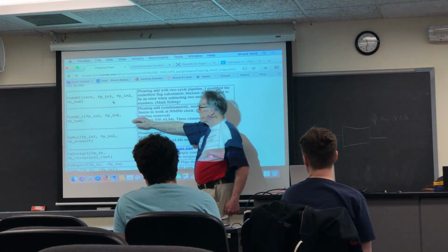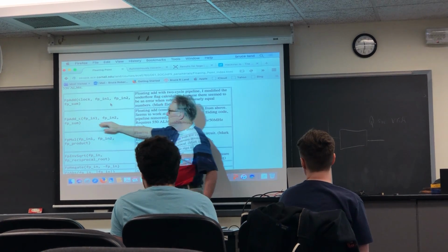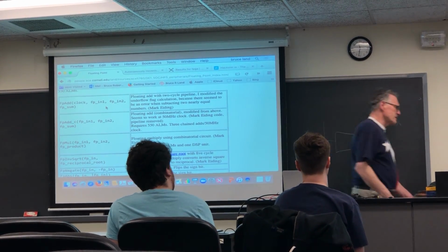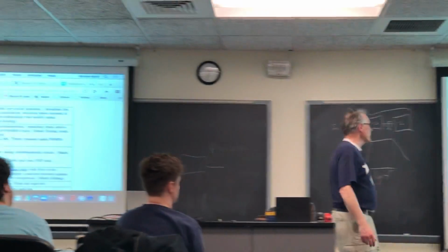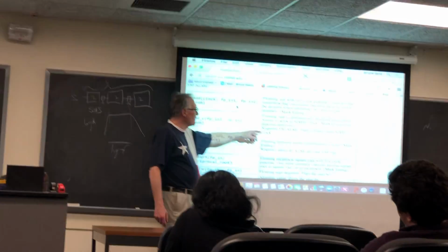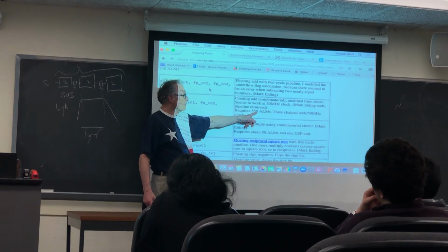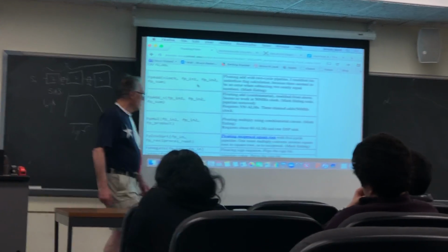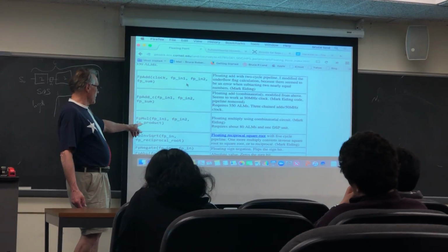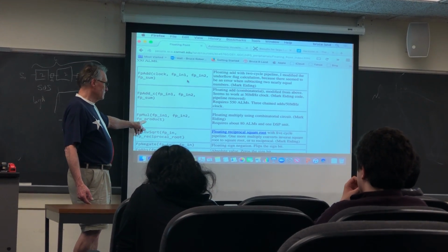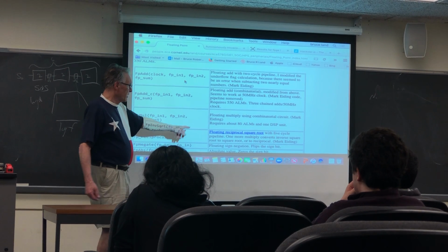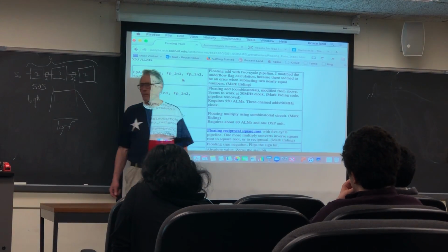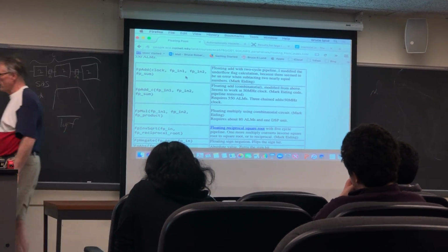Although I rewrote it as a combinatorial add to see how fast it really was combinatorially, and it runs at something like 100 megahertz combinatorially. It requires about 550 ALMs per adder. Whereas a multiplier runs just fine in 1 cycle, requires about 80 ALMs and 1 DSP unit, which is a lot of logic, but you don't have to build it.